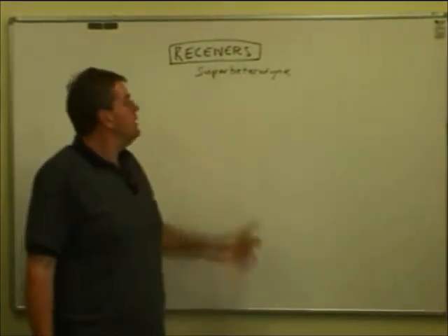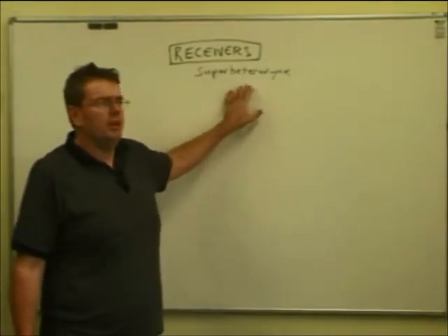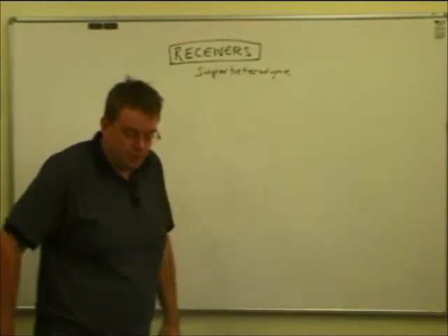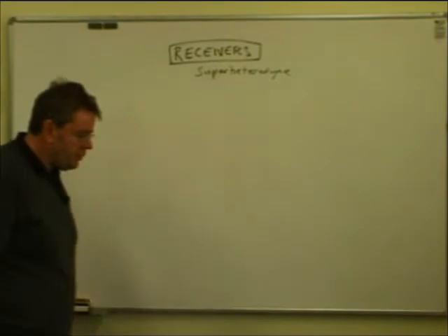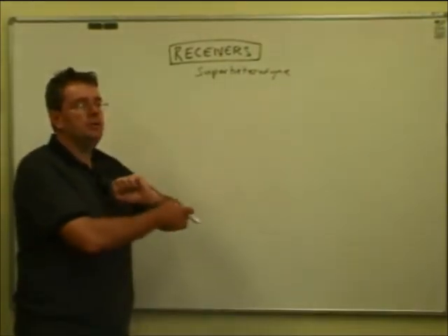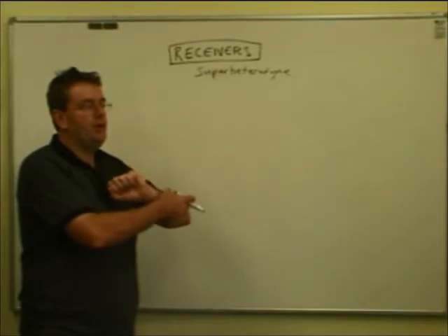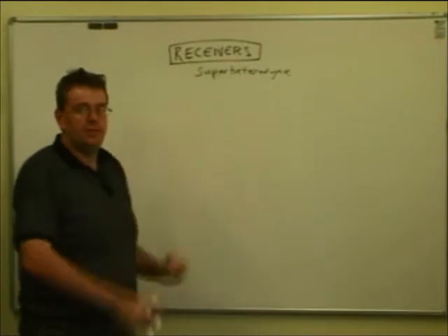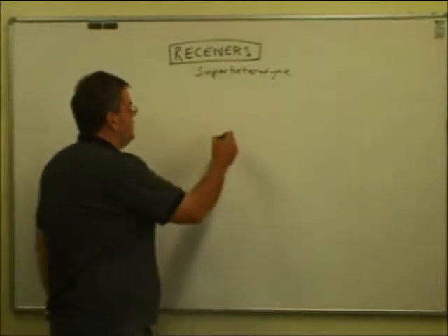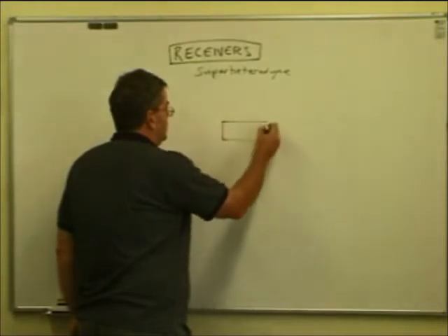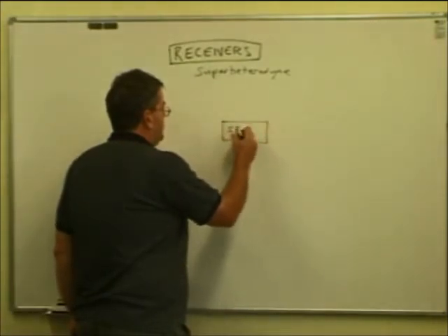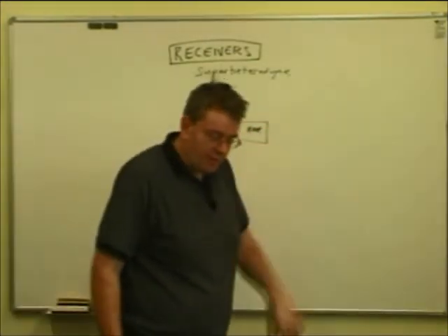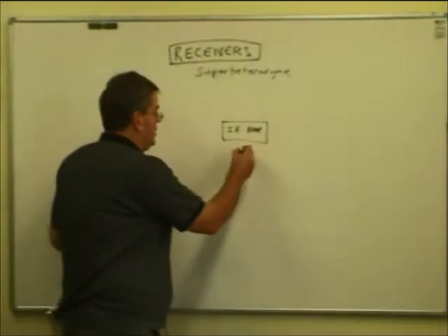It uses the technique of heterodyning, the idea that you can actually use two signals and combine them together and shift them to a third point. I think a good example to illustrate this is if we want to operate a receiver in the 80 metre amateur band at 3.5 to 4 megahertz, and we use what's called a 9 megahertz intermediate frequency. So we'll just start in the middle. We have in here an IF, or intermediate frequency amplifier. It's an amplifier that's designed to work around the frequency we want. In this case, it'll be 9 megahertz.